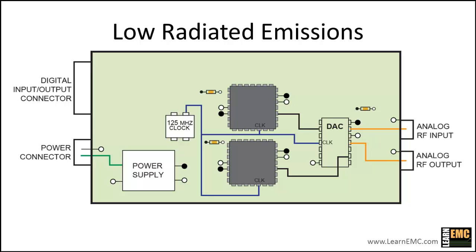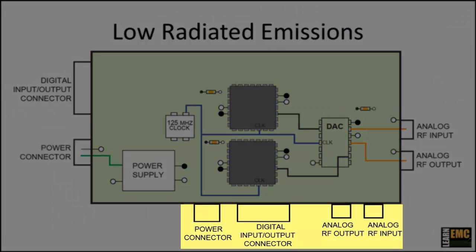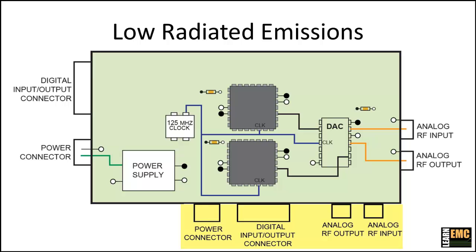We want to try to get those connectors closer to each other, ideally on the same side of the board or in the same corner of the board. In the new layout, let's put the connectors along the bottom edge of the board like this. This does not eliminate the voltage between the connectors, since they're still referenced to different points of a current carrying ground plane. But this placement minimizes the voltage differences.